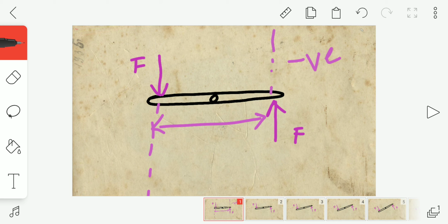The lines of action of both forces are parallel to each other, but the directions of the forces are opposite, with equal magnitudes. The effect of this force will be equal to this force, applied on the body such that a rotating effect is obtained. The rotating effect obtained here is pure when compared to moments, so a couple is also known as a pure moment, right?